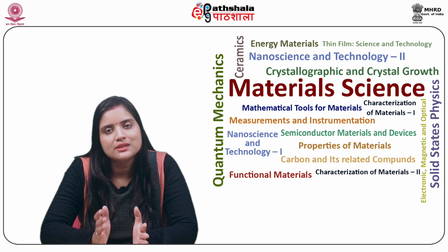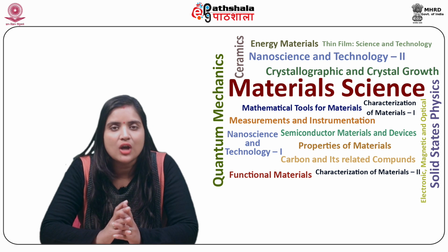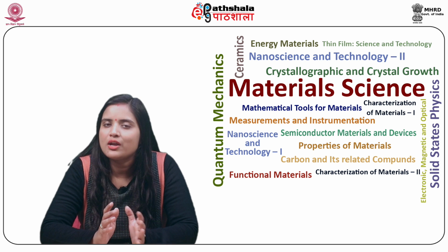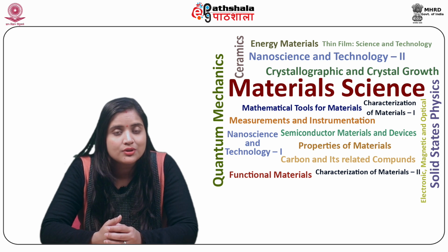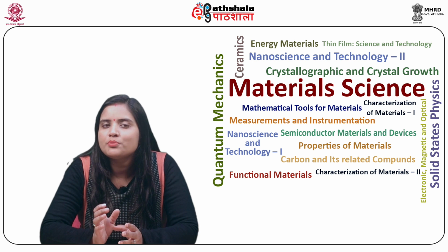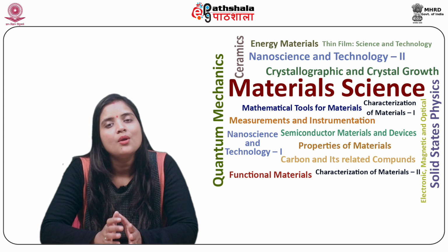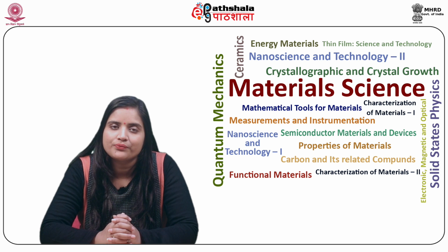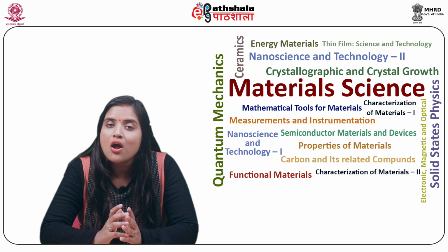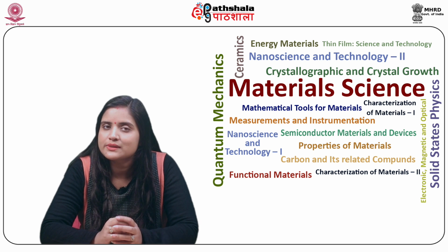Owing to the presence of positively as well as negatively charged ions, the electrolyte conducts ions. The electrolyte is prepared by dissolving the salt of the desired metal to be deposited in a suitable solvent, that is, most commonly water. The solvent can also be an organic or ionic solid for specific electroplating processes.